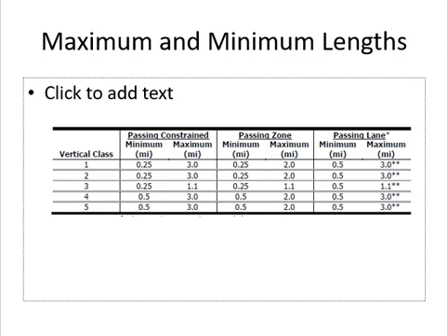One thing which I mentioned earlier, I showed you in the table as well, which is the vertical class. The code which they gave according to the terrain of the highway. So this is the table which tells you the code of the vertical class. Vertical class 1 means, so we said we have 3 types of highways, right? 3 types of segments. The segments which have passing constraint, passing not allowed. Segments which have a passing zone, passing is allowed. The segment which have an extra lane for passing, right? 3 types. So in each one of them we have a different coding system.